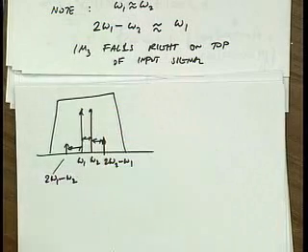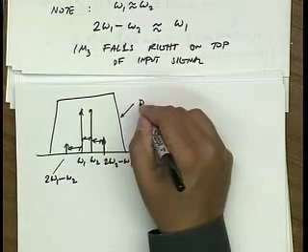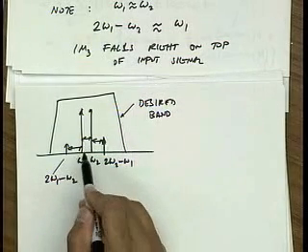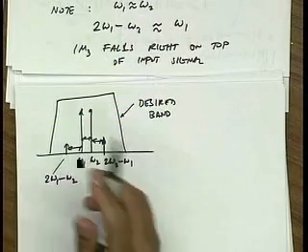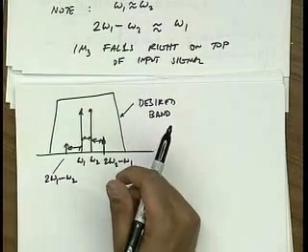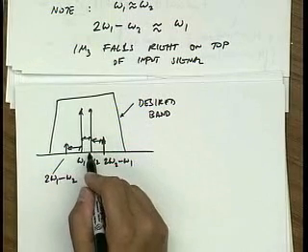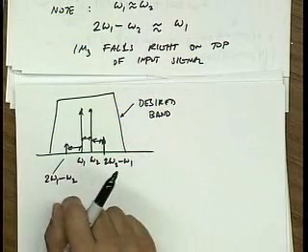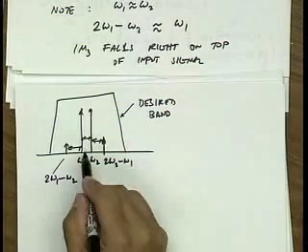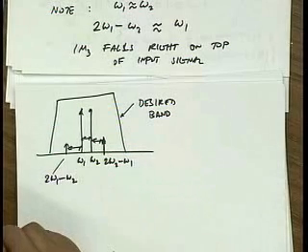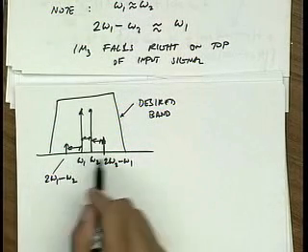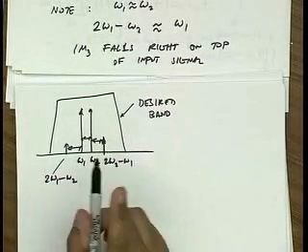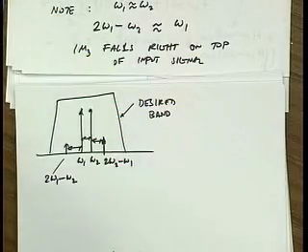Like this might be the band that you're interested in. And these two tones could represent two modulation components, right? I mean, let's think of a very idealized scenario. Let's say these two tones correspond to two people singing a pure tone, right? Two opera singers producing two tones. The harmonics are out of band, but now this nonlinearity produces two more tones. So we have these two baby opera singers who weren't supposed to be there. And they fall in band. That's the key point.